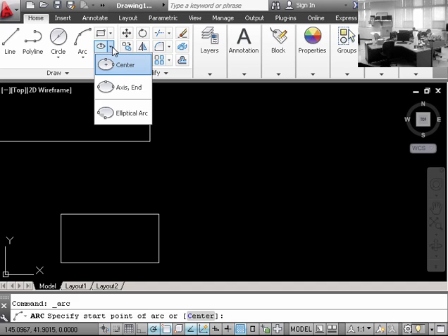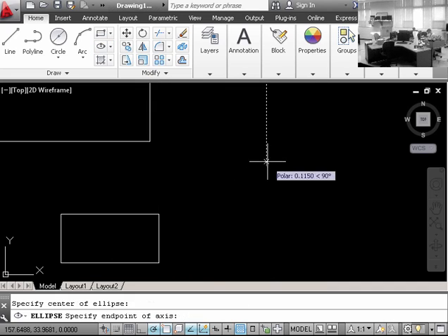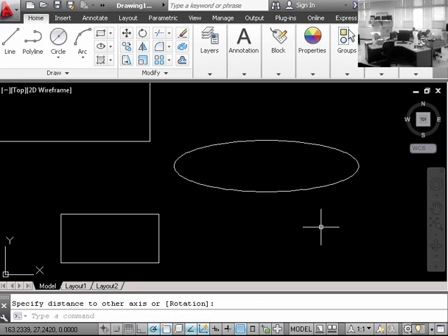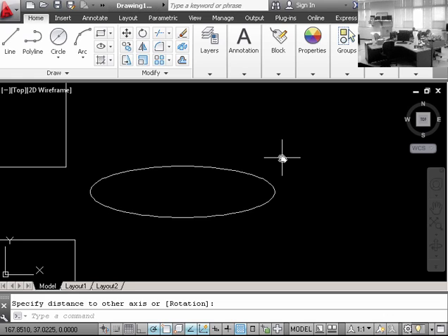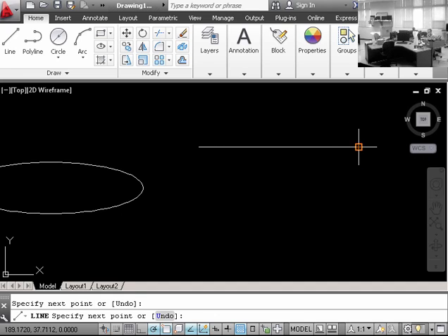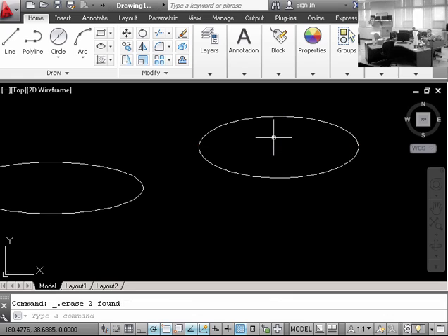We don't use the ellipse as much because it's not really a fabrication type of thing. One of the things that ellipses are used very well for, though, is material removal. When I want to reduce weight on parts, I can use an ellipse. They're structurally useful, so are circles. And also we use it a lot in additive manufacturing to not have waste material and do stress distribution. Ellipses work pretty easily though. One of the best ways to make an ellipse is to make the skeleton for it, and then use the ellipse command to essentially click here, click here, click here, and delete, and you have your ellipse made. Okay? They're usually based on horizontal distance and vertical distance.